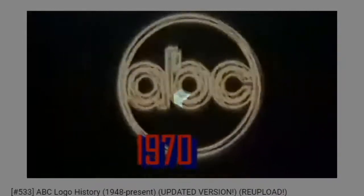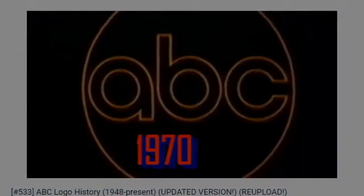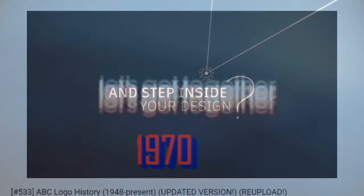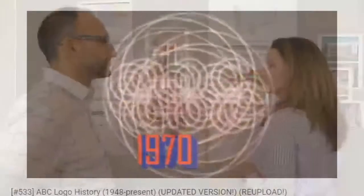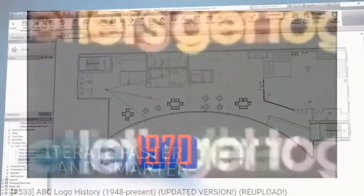All right, now, if you do not need a finish, but just a slab depression, you can create it with an in-place void extrusion. Select the Architectural tab in the ribbon and click Component Model in Place. Choose the Floors category and create a void extrusion. We need a slab depression. Remember to use the Cut Geometry tool to cut the void from the floor before finishing the family. As an alternative, you can create a floor-based generic family that contains a parametric void extrusion. You can download the file C14 Slab Depression RFA as an example of this type of family from the book's webpage.